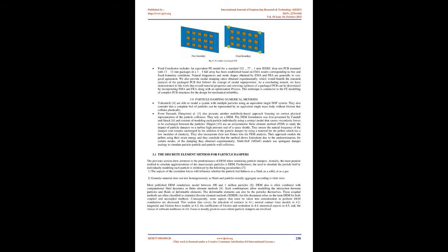They rely on a DEM. The DEM formulation was first presented by Cundall and Strack 6 and consists of modeling each particle individually using a contact model that causes viscoelastic forces to be exchanged between the particles.